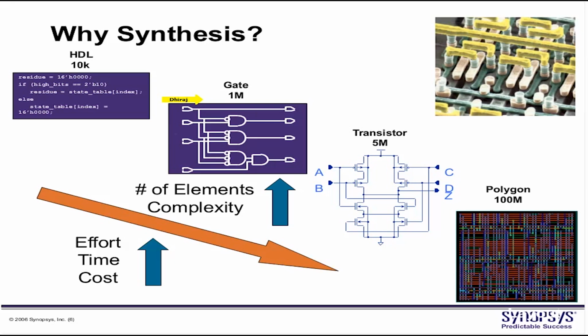So for a full chip, an HDL will have a few hundred files with some thousands of lines of code. And then when it goes through gate level, it expands into 1 million gates which are hooked up together. Since the gate level database is not the one that is manufactured, we convert this gate level database into a transistor level schematic using physical design tools.